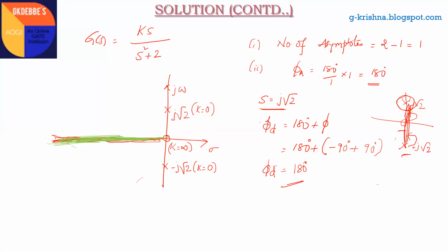What about the angle of departure of the conjugate imaginary root? For the conjugate pair, it will just take the negative sign, that is minus 180 degrees. So this pole will depart with an angle of plus 180 degrees to the left side, and this one with minus 180 also to the left side. Since these two poles depart with 180 degrees and are complex in nature, these roots must break in onto the real axis. Hence, the root locus diagram will be in this manner.